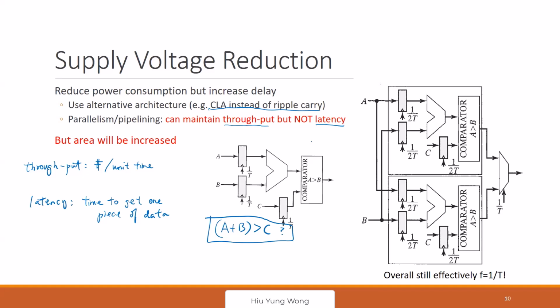Okay, now if I try to do it all at the same time, this is the register. We are going to learn it very soon, right? I need to complete the calculation within T period, right? Because here I go to another register, right? So from here to here, you need to finish in T, right? Within T seconds, you need to finish this computation. And because of this, I can clock my frequency at 1/T.